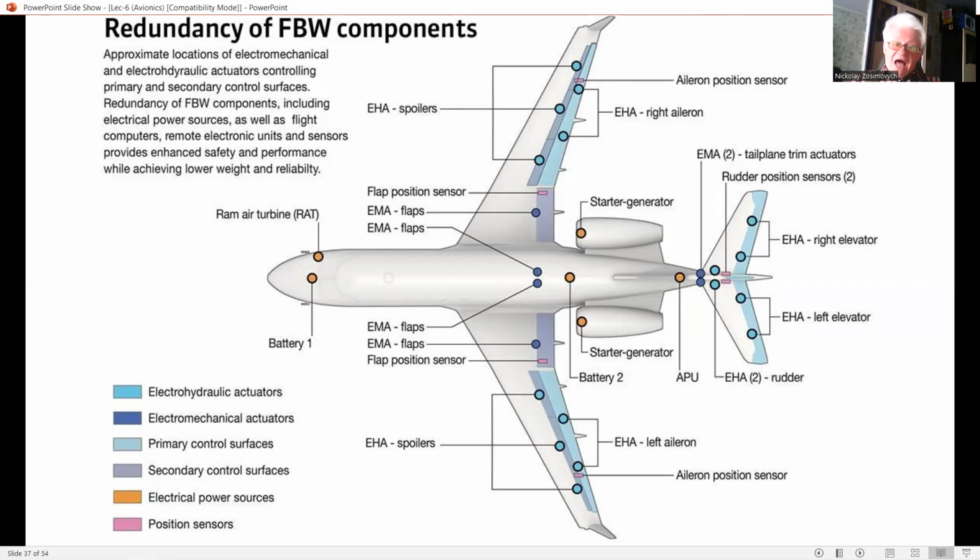And failures are therefore detected by the cross comparison of the parallel channels and majority voting on the odd man out principle. The quadruplet system is thus able to survive two failures by majority voting and disconnecting the failed channel. The system degrades to triplex redundancy after the first failure and duplex redundancy after the second failure. A third failure results in a fail passive situation, the good channel counteracting the failed channel.